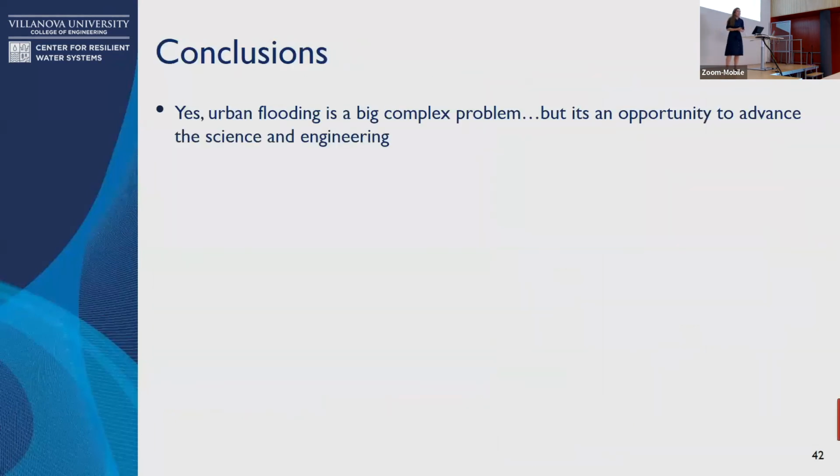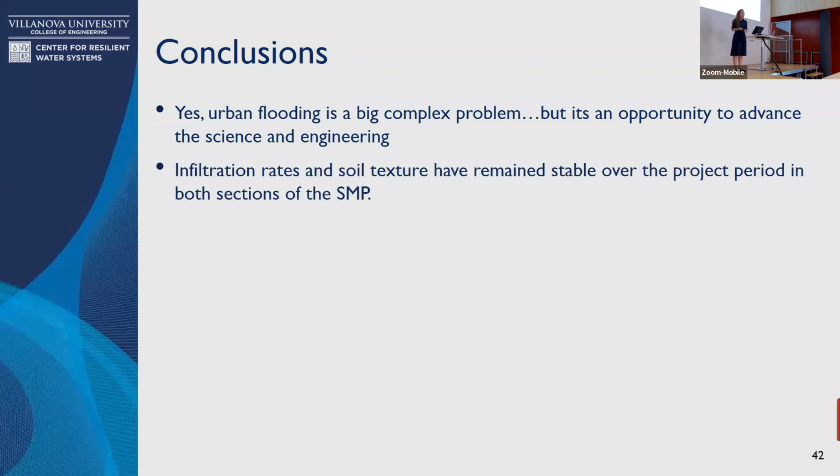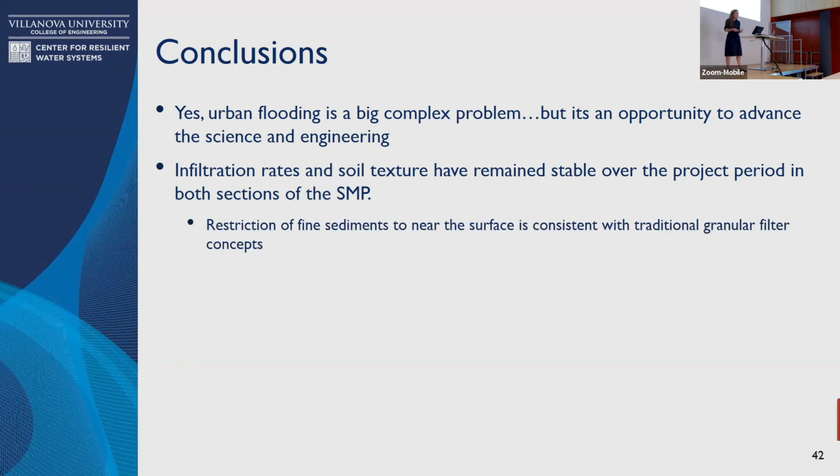Okay. So in conclusion, urban flooding's a real big, complicated mess. It's a big problem, but it's a great opportunity for us as engineers to understand and advance the science and engineering more. Infiltration rates at SPA through this project period are really great. They've maintained the same, but in understanding why they've maintained their rates while others haven't has allowed us a little bit more understanding of the restriction of sediments to the near surface to act like a granular filter and apply filter dam concepts. Testing is underway to evaluate the limits of this.